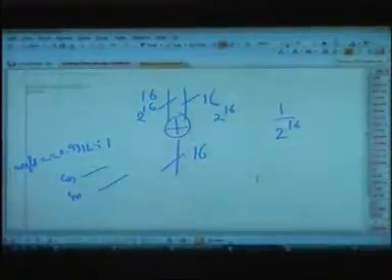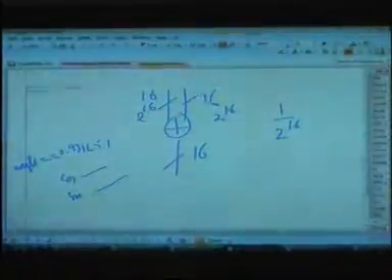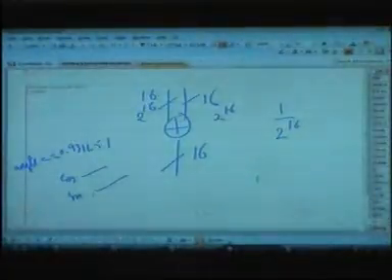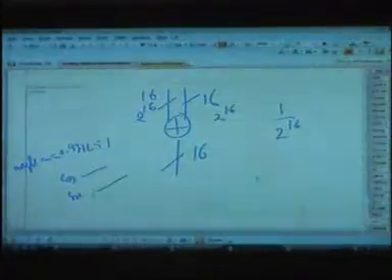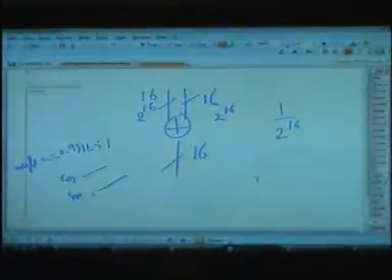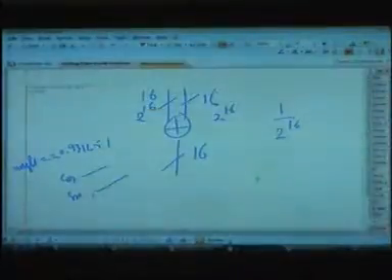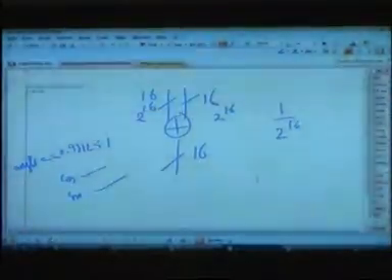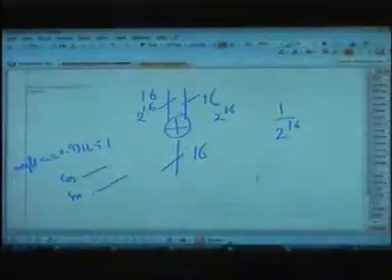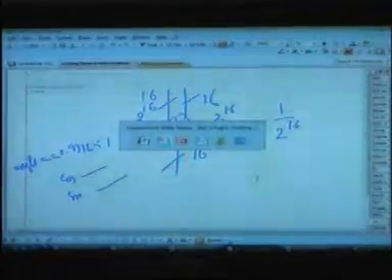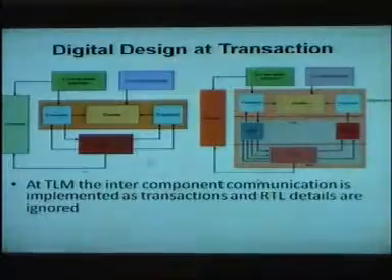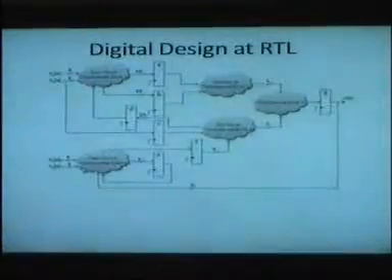But the important aspect is that once people are designing smaller components, they quickly jump up, say, oh, it's working, let's now integrate it into a bigger and bigger design, and then they start finding problems, and then they need to go down and see where the problem is. So whenever you design a little thing, try to do exhaustive testing on the little components, because you cannot do exhaustive testing on a bigger design. It's impossible. It will take many days to maybe one month to test a simple design with so many inputs. So it's always better that we know these things, that coverage is important, and there are tools, and we'll spend some time learning about them.